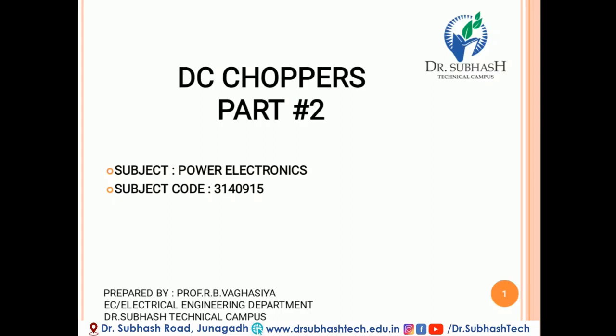Dear students, we all know that DC chopper circuits can be classified in three different ways. First one, buck converter; second one, boost converter; and third one is the combination of buck and boost converter. We know that a DC chopper circuit converts a fixed input voltage into a variable DC voltage, right? Now we can categorize the three different DC choppers.